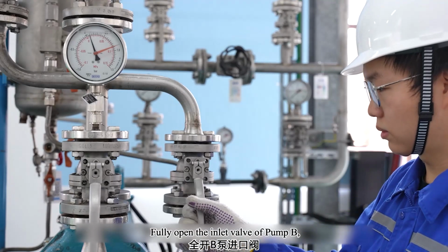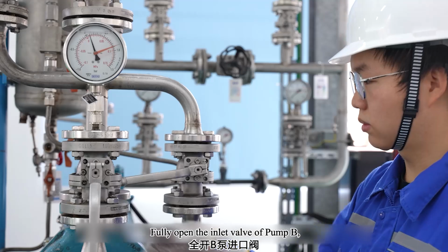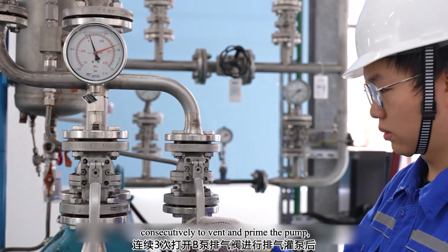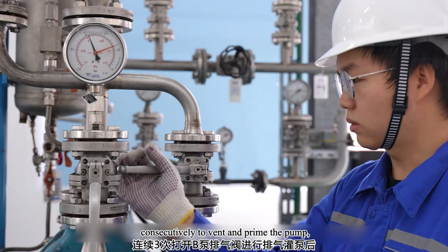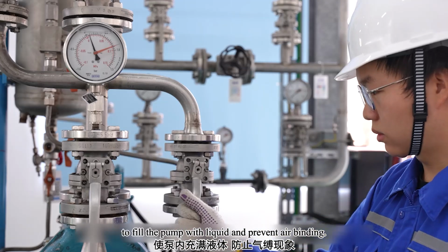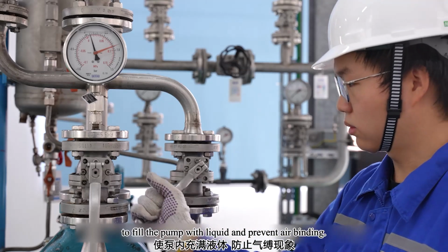Fully open the inlet valve of pump B. Open the vent valve of pump B 3 times consecutively to vent and prime the pump, then close the vent valve to fill the pump with liquid and prevent air binding.